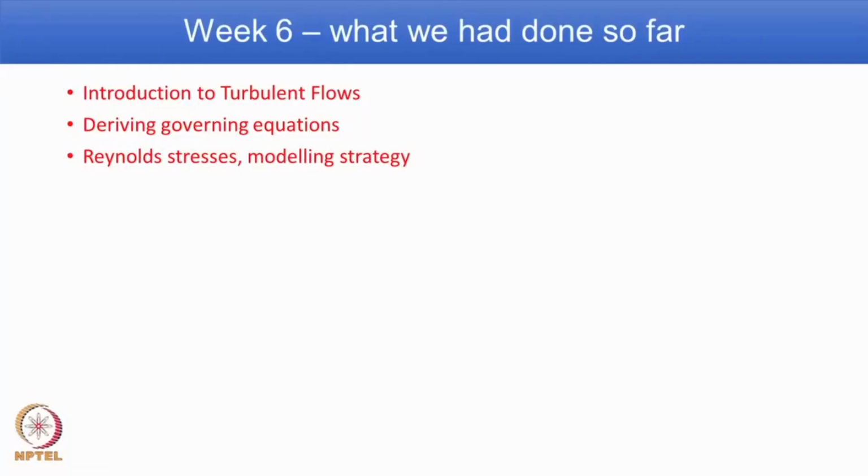Greetings and welcome again to this course on CFD. Last class we had seen deriving governing equation, Reynolds stress, modeling strategy. In particular, we came to know about standard models, standard K epsilon and standard K omega model. We also listed different proposals available in the literature in standard K epsilon and standard K omega model to improve the performance. One such proposal was low RE model,